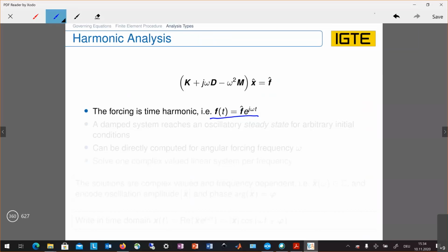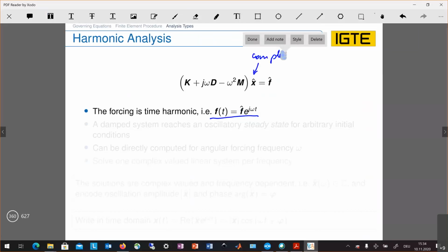We have to be careful then clearly that this value we get out more or less is complex. Also, we get out amplitude and phase of the mechanical displacement for all three components, X, Y, and Z component in all the finite element nodes.